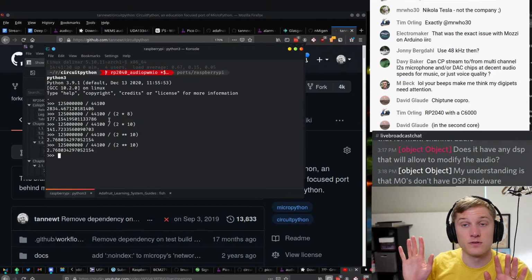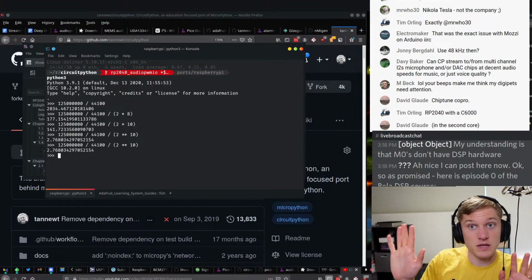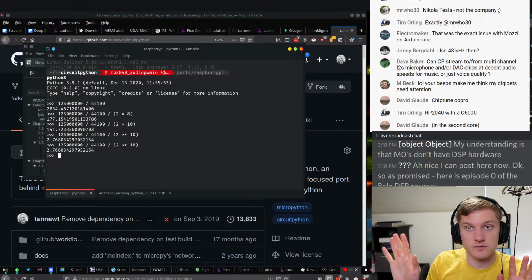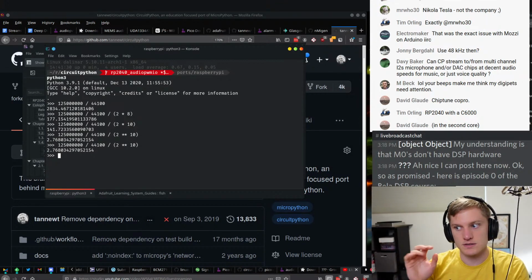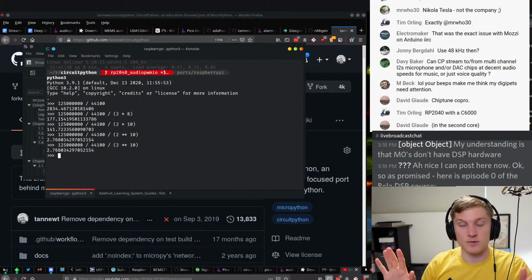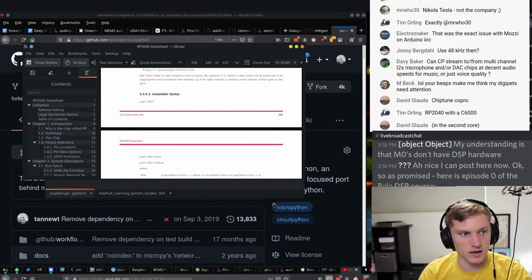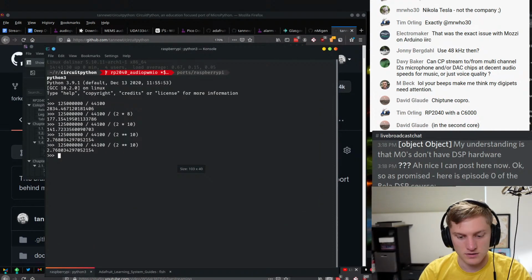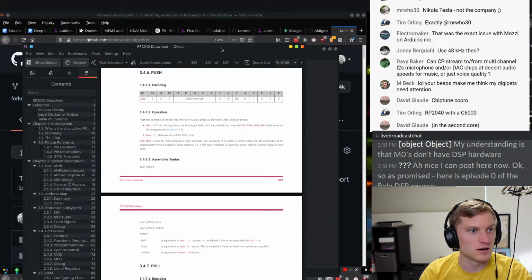So the way that I'm going to have audio PWM IO working is that the PWM will just be clocked at a fixed frequency with a fixed top value. So it won't divide down the 125 at all. It'll just divide it by whatever the top value is. And then I'm going to copy in, at the sample frequency, the value that I want the PWM to be outputting. And there's this really cool feature of the DMA, and it's almost a footnote in the datasheet here, I think.